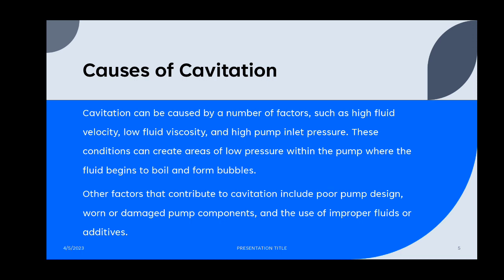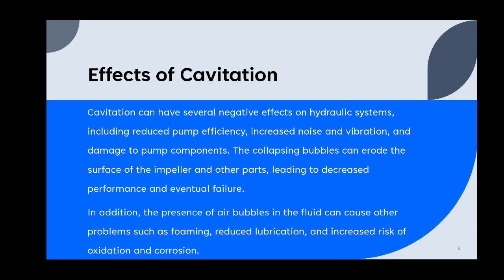Let's move on to the effects of cavitation. What will be the effects of cavitation? Cavitation can have several negative effects on hydraulic systems, including reduced pump efficiency, increased noise, as well as vibrations, and damage to pump components.